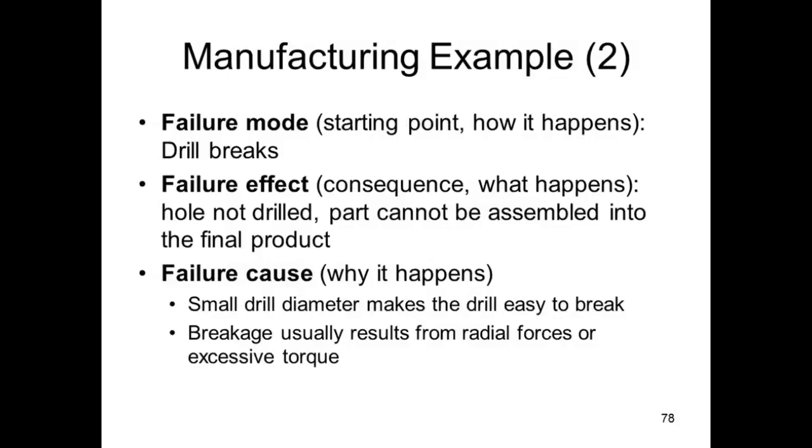Failure cause, why it happens. Small drill diameter makes the drill easy to break. Breakage usually results from radial forces or excessive torque. That I had to look up. Again, Shigeo Shingo is focusing only on controls to detect the drill breakage. I did some additional research so I could cite failure causes to make this into an example.